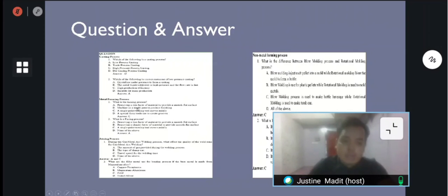No. In the turning process, when you are using a lathe machine, you cannot remove a thick layer of material, because it will break the tool bit or the workpiece itself, or you can burn the tool bit, wear it off or break the sharp edge. I have done that, and yes, I know that is bad. Machining in a single pass to produce a finish. No, you cannot finish the turning process in a single pass.